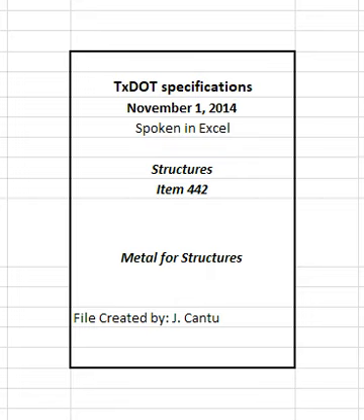2.6 Pipe rail. Pipe includes special extruded and bent shapes. Provide pipe that is rolled, extruded, or cold pressed from a round pipe or flat plate, and of the section shown on the plans. Ensure the design of the cold press and dies results in a pipe of uniform section free from die marks. Cut the pipe to the lengths required once it has been formed to the required section. Make the end cuts and notches at the angles to the axis of the pipe required to produce vertical end faces and plumb posts when required by the plans. Provide a neat and workmanlike finish when cutting and notching pipe.